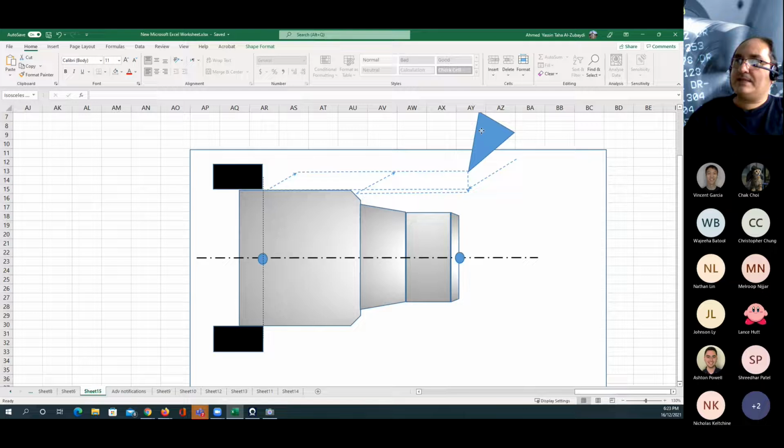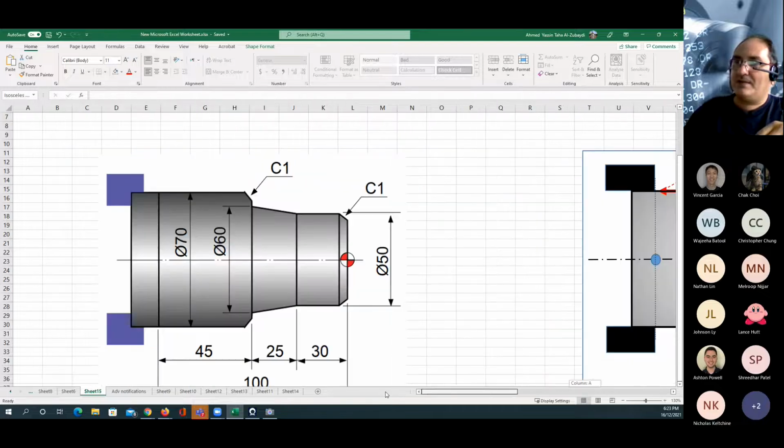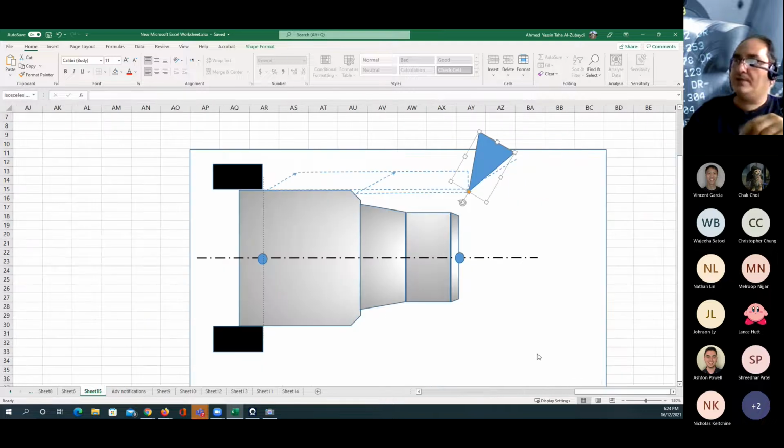So we said now we are standing here. We're going to go down to the new diameter. This 70, I'm going to take it to the next diameter of 60. Well, this one is, I remember it was 60. Actually, I'm doing a wrong thing. Yeah, 60. So I'm going to do the next cut to be 68.